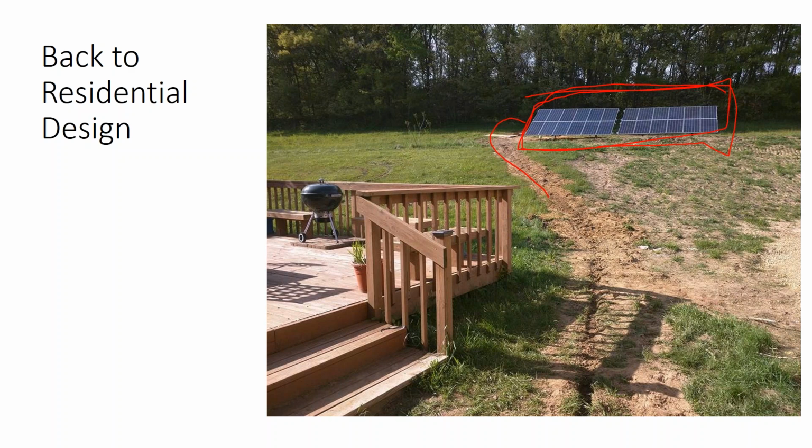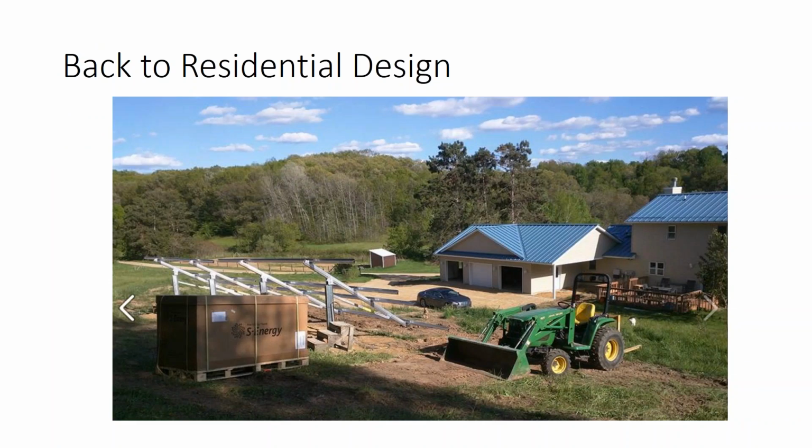So what do we do under that scenario? Well, the first is we're going to select an SMA inverter. The reason we went with the SMA inverter is because SMA also has a battery inverter in their product line, so that we can seamlessly integrate a battery down the road. Now, this is not just typical for SMA. We see SolarEdge doing the same thing. But that's really neither here nor there.